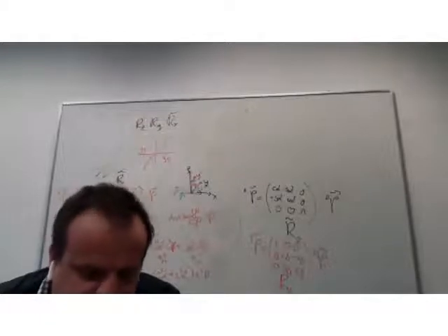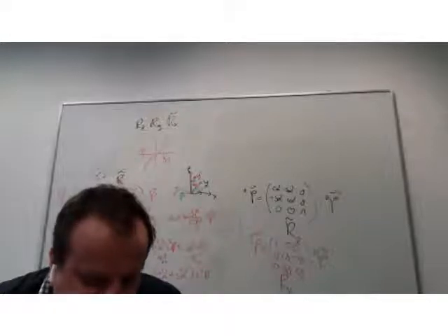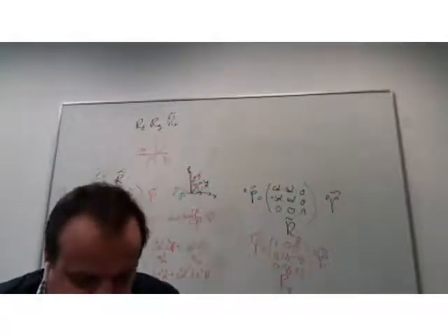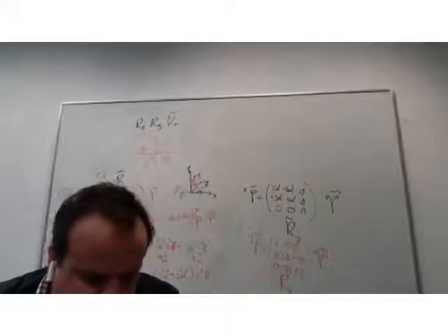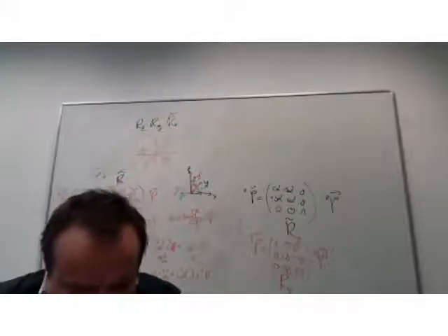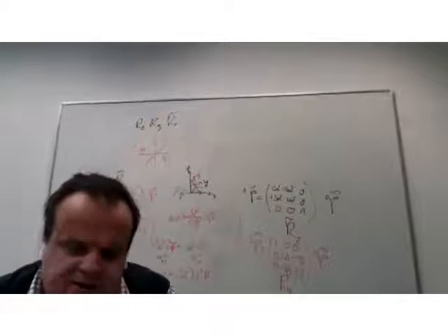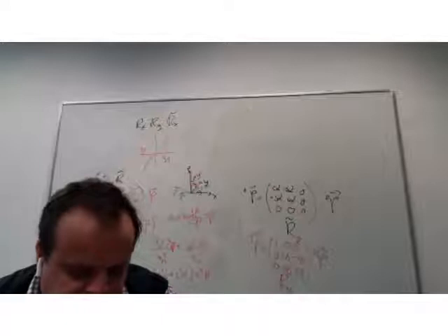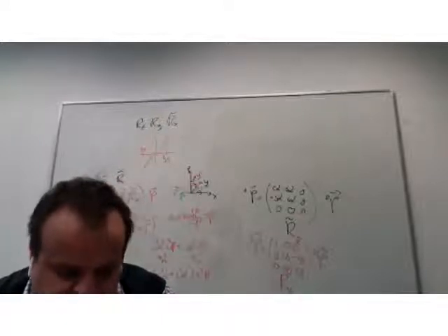So just by looking at the correct elements of the multiplication here, we can extract the numerical values of the so-called Euler angles of this representation. And the last one is gamma in the same way. So we see that the 2 other parameters basically require a division by the cosine of the beta result. And this brings us a problem.